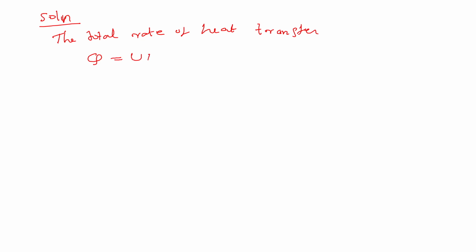So now we go to the solution part. The total rate of heat transfer Q will be U A LMTD, so you have to calculate the LMTD for this system. First we will calculate the Q value.